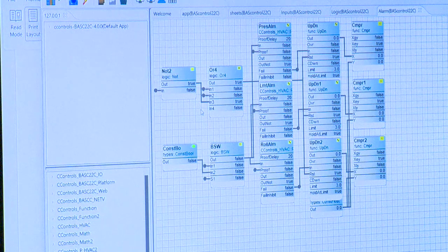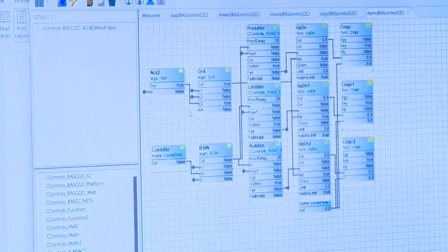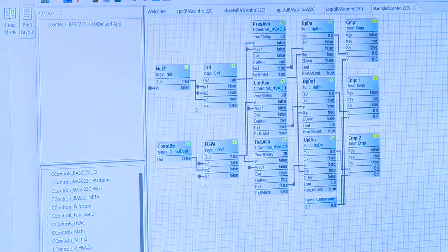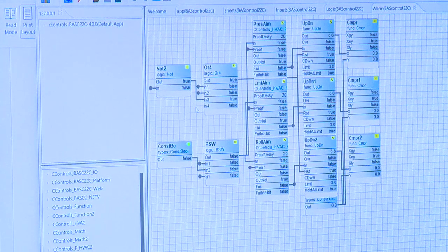And this program actually had flash codes built into it. So think about a furnace controller, and they were like, hey, we want to have a flash code. So they took an output and made an actual flash code happen for their alarming, just like a furnace controller board. But the control strategies are very simple. They're thermal resistive elements, right? And you can string up all the controls, operate your inducers and all your fans, and remove that furnace controller board. It's a cool project to do.